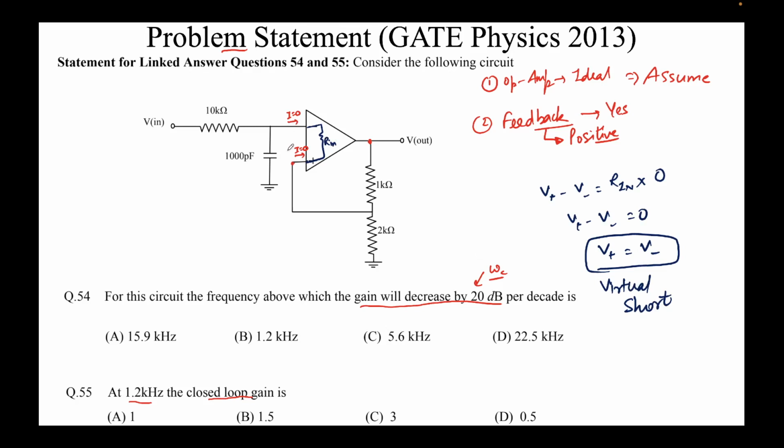No, there isn't. It's just the peculiarity of the op-amp that it appears as if the inverting and non-inverting terminals are at the same potential, and we denote this effect by using a dashed line between these 2 points. So this denotes that these 2 points are at the same potential, not joined by a wire, just sitting at the same potential.